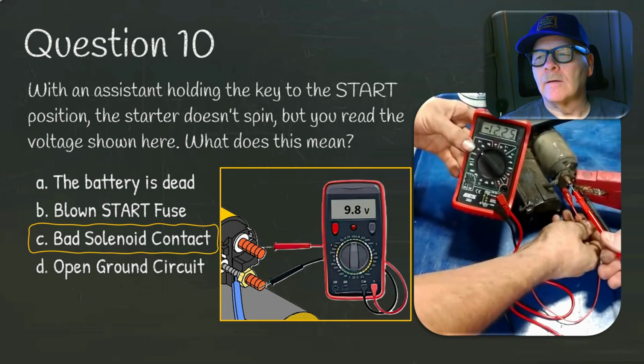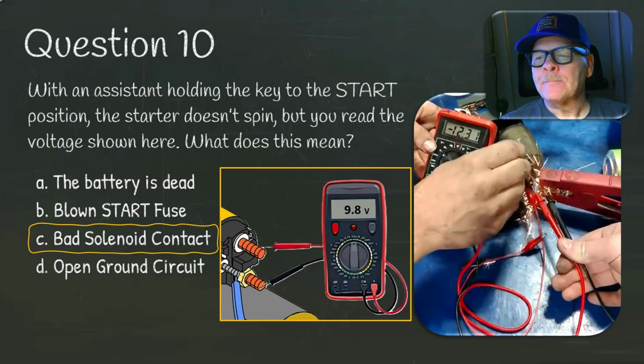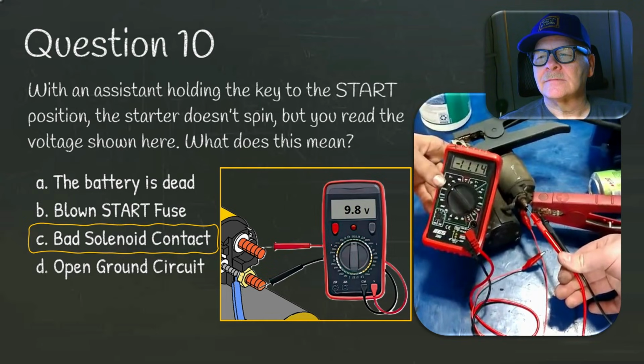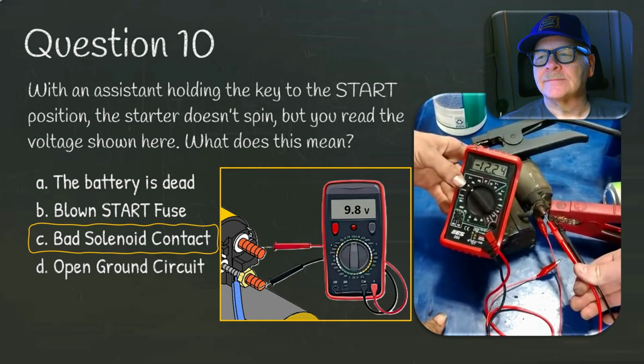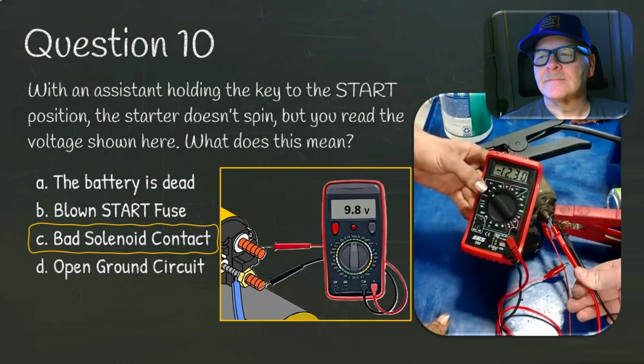Now you can actually run a screwdriver across the two big terminals, and it sort of spins, but it barely will. That means that voltage drop and the low voltage from it has burned the starter up. So we've got to get a starter, but the stupid parts house doesn't have a starter for an Impala in stock. Who in the world would have ever thought that?